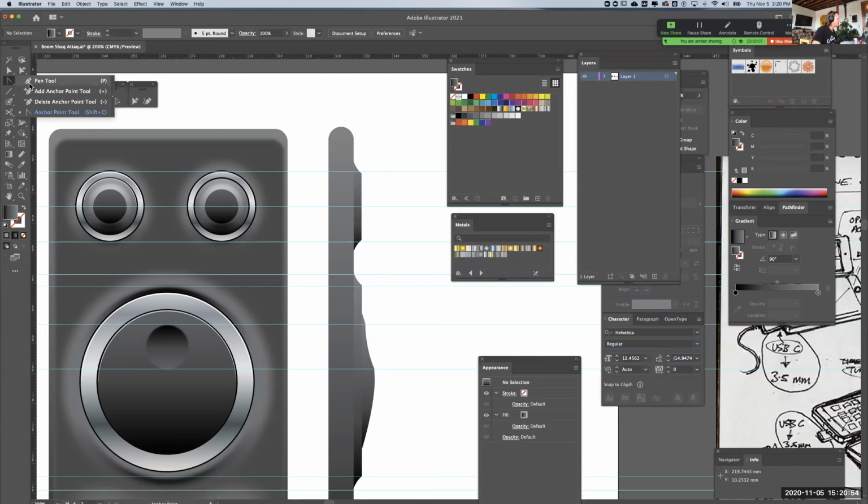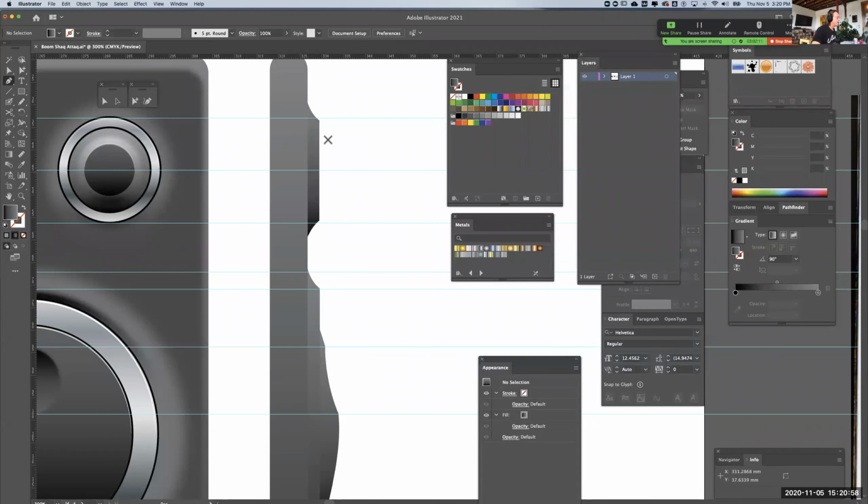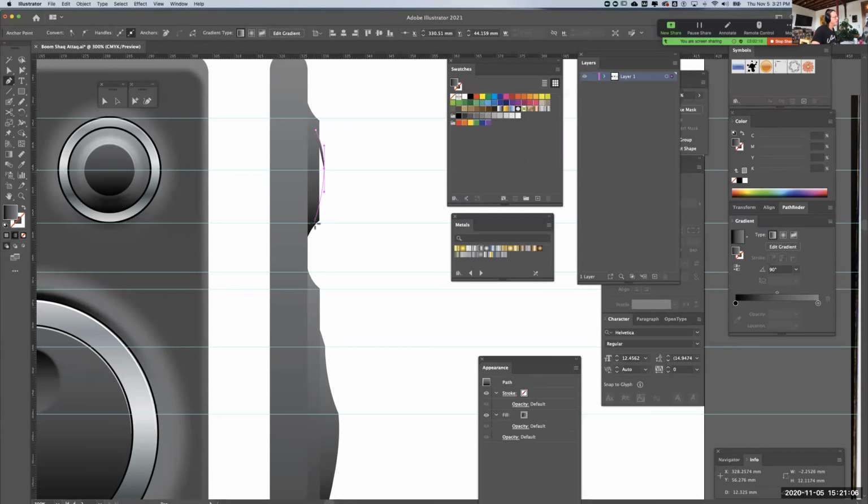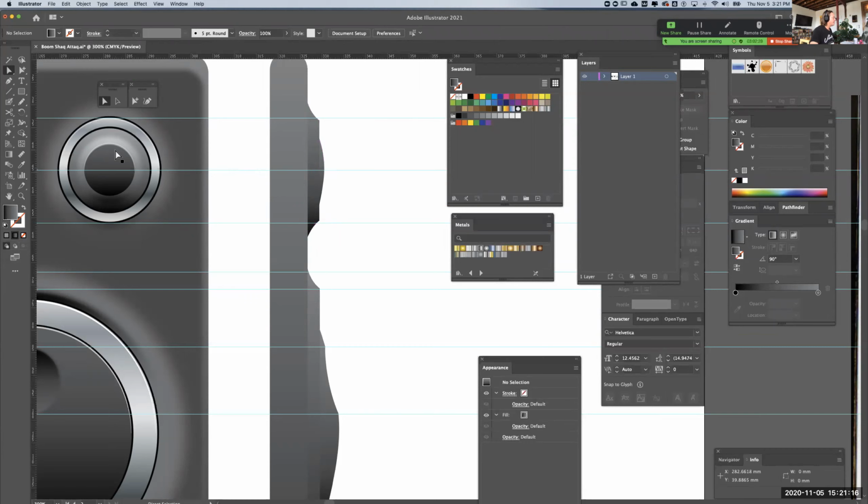This is how I'm using the path tool. I haven't shown you this yet, but this is the pen tool. So I'm going to click inside here. This is about halfway in there. And I'm just going to move that to the very back. Control X, move it to the back, Control B for back. So there's my knob, and then it's going to do something like this.